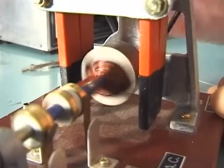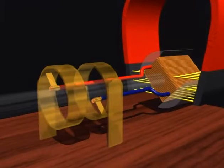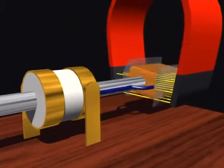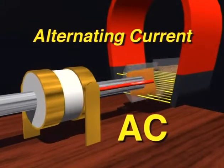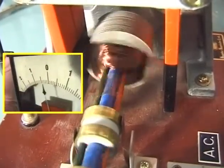We can also look more closely at how the coil actually connects to the circuit now. We can see that one end of the coil is always connected directly to this ring, which is always connected to this part in the circuit. As it passes this pole of the magnet, the current will go one direction, but when it cuts the magnetic field of the other pole, then the current will change because it's still connected to the same point in the circuit. This is called alternating current, or AC. We can connect this up to the galvanometer and see that the current actually changes direction as we turn the coil around.